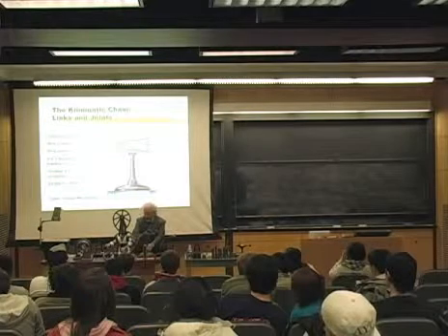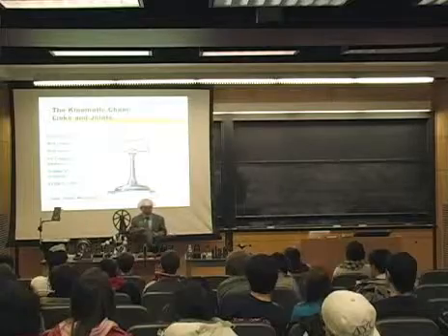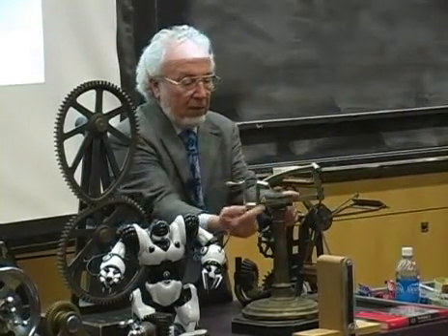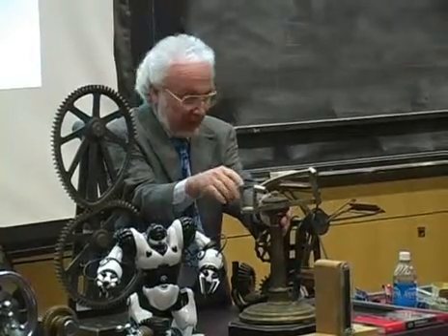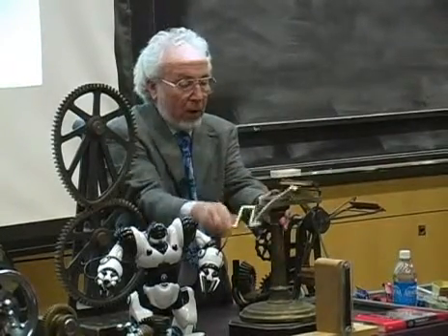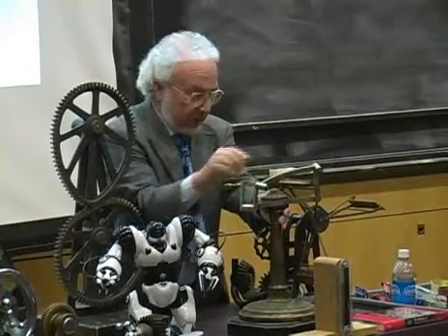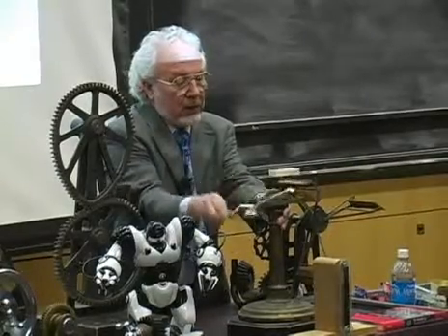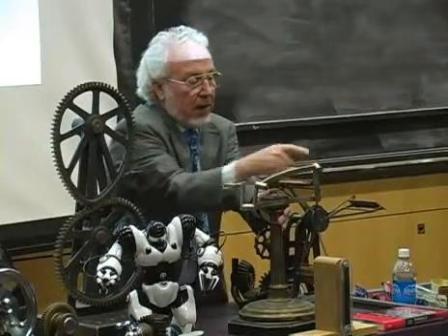So, if we think of a so-called four-bar mechanism, we have 1, 2, 3, 4 links, and we have 1, 2, 3, 4 joints, and we can turn one of these, and one of them moves in a circle, and the other one moves in an oscillatory or a rocking motion. This is called a crank rocker. So I'm turning this particular link, and this one is oscillating this way.